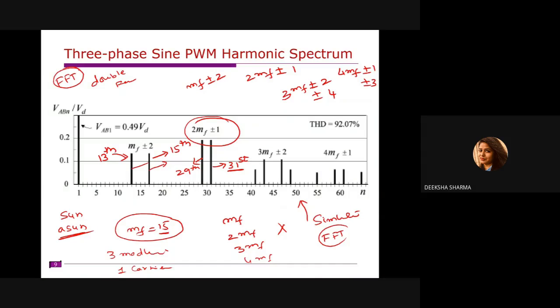Now what is the advantage of synchronous PWM? When you have synchronous PWM, if you observe here, these are almost 0. Practically these are some minute values, so that's almost 0. In case of asynchronous, we have some random values, or some small magnitudes will appear here, or some interharmonics will appear when it is asynchronous PWM.